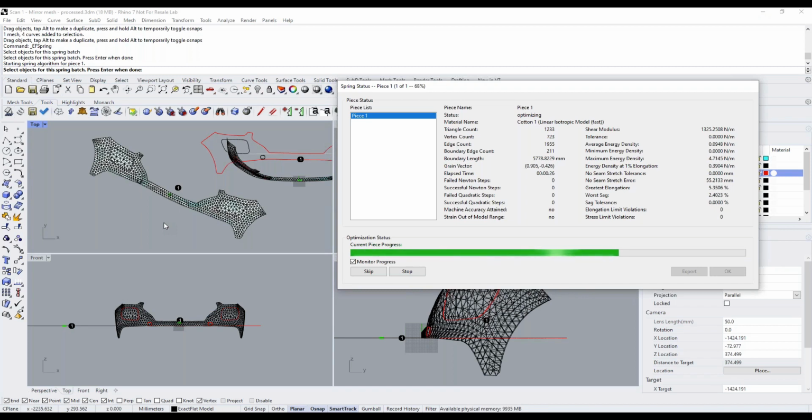Okay, Adam, I'm hoping that answers your question. If you want to know more about this, we're happy to talk about this in more detail. The reality of the ExactFlat flattener is it's not a projection flattener. What it does is it actually distorts the 3D object through nonlinear transformation or deformation into your 2D pattern piece, such that when you wrap it back on, it fits perfectly. So the cutouts have to go through the same deformation process in order for them to be properly applied.